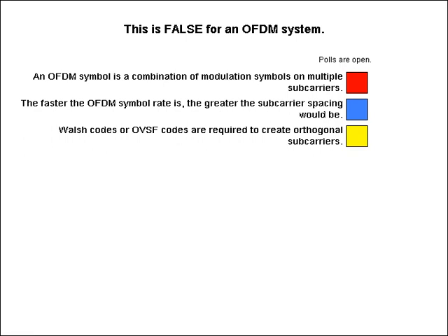Okay. So, faster symbol rate meaning we have many OFDM symbols. So, the symbol is becoming shorter. OFDM symbol is becoming shorter. So, now what is the relationship between the subcarrier spacing and the symbol time? For option number 2, think about the relationship between the symbol time and the spacing. If symbol time goes down, what happens to the spacing? Does the spacing increase or decrease?